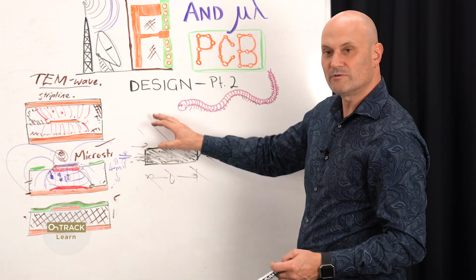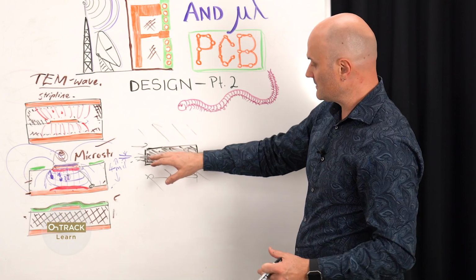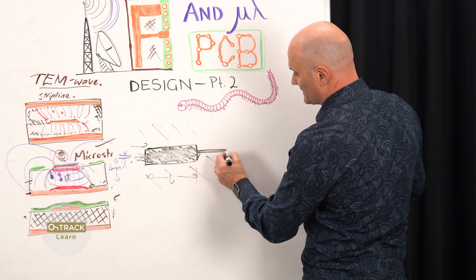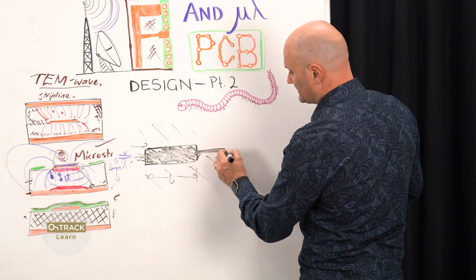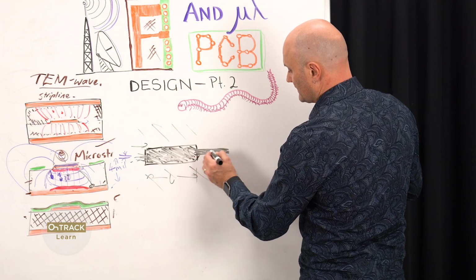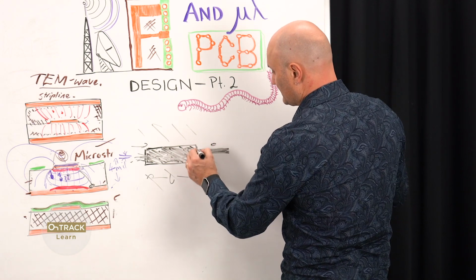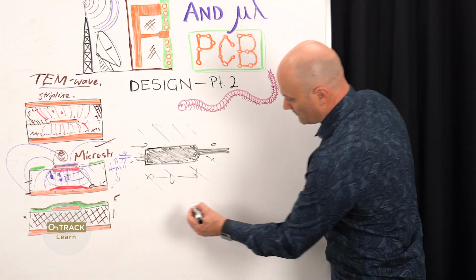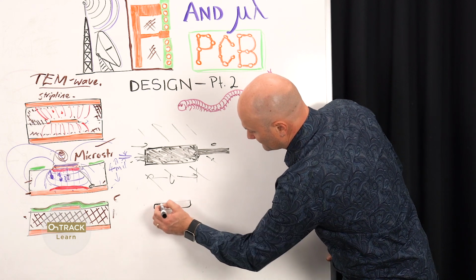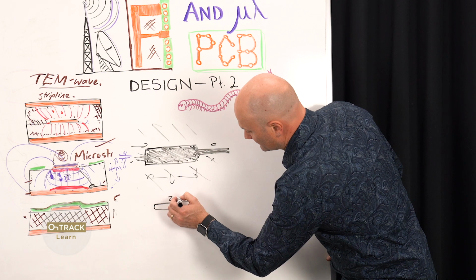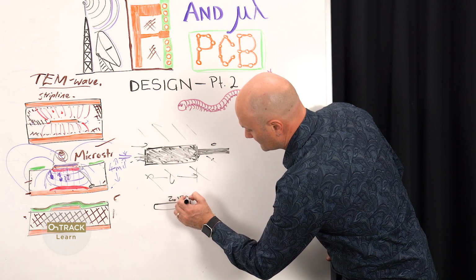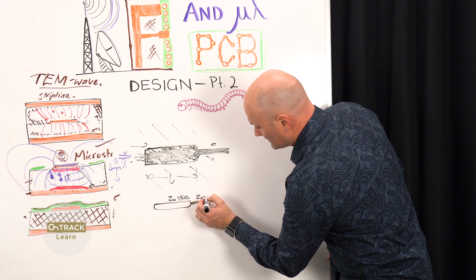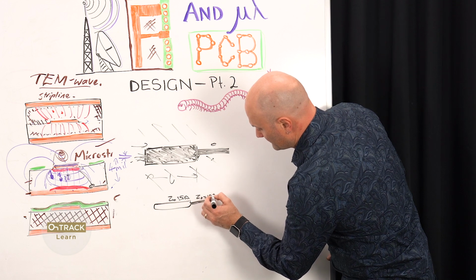It's maybe a 2.4 gigahertz wave going into this trace, and then somewhere down the line we come to a much higher impedance trace that's narrow. Maybe we have to neck it down to fit in between two pins or something. Well, this here is an impedance anomaly, and we know what happens when we create a transmission line of one characteristic impedance. Let's say that Z0 is 50 ohms, and then here we have a narrower trace. Maybe the Z0 of that one is 100 ohms.